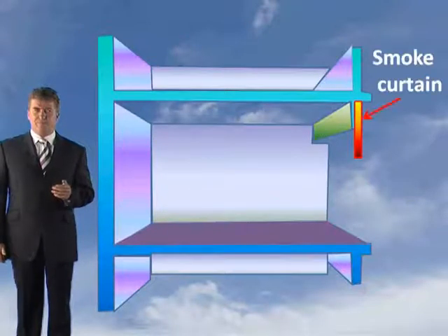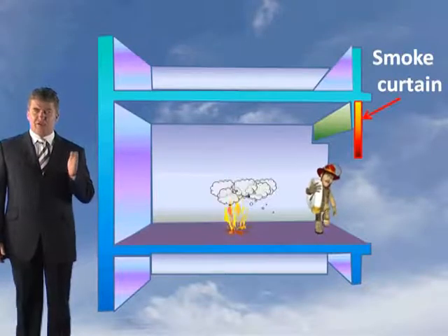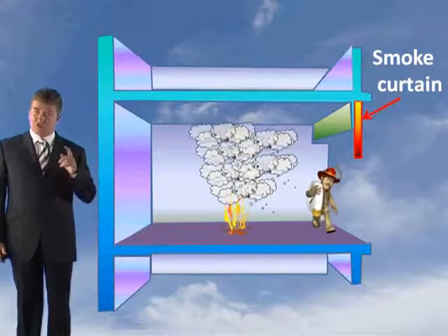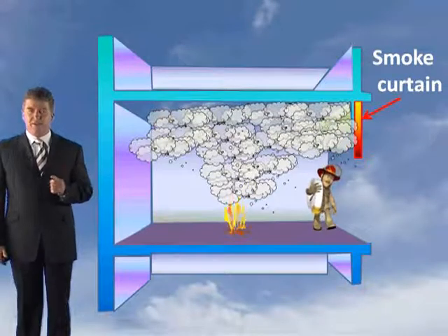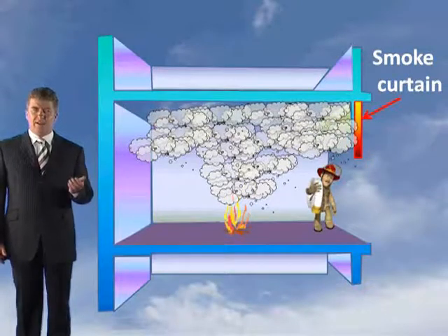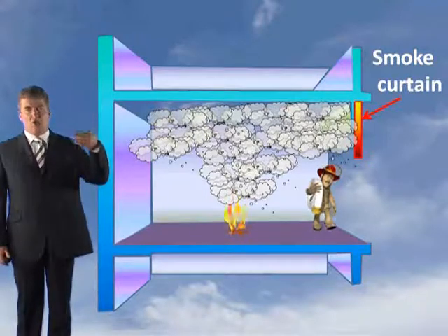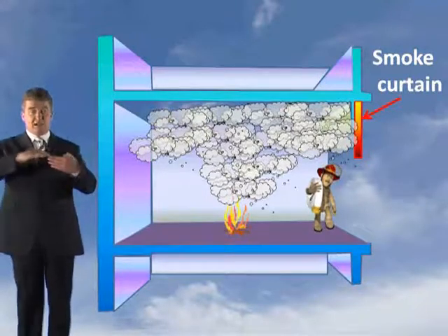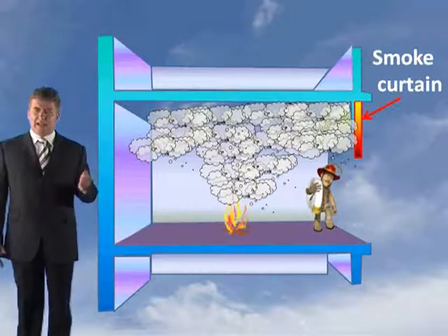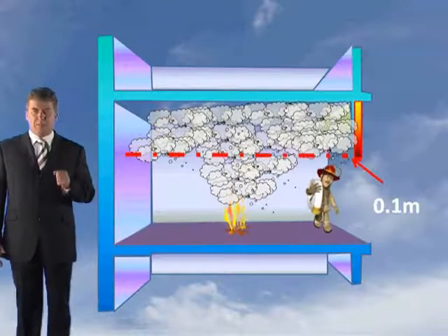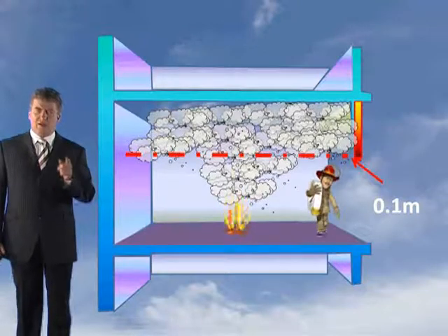And you've also got those which act to contain a gas layer which does not extend below the bottom of the curtain, as shown here. For example, you've got reservoir screens and channeling screens. In other words, they only drop low enough to maintain the smoke layer in them. That's what they do. And these would normally be designed to extend at least 0.1 metre below the calculated smoke layer depth.